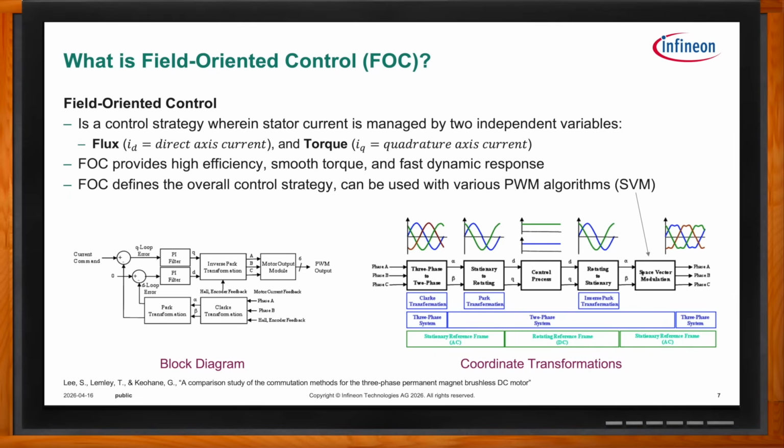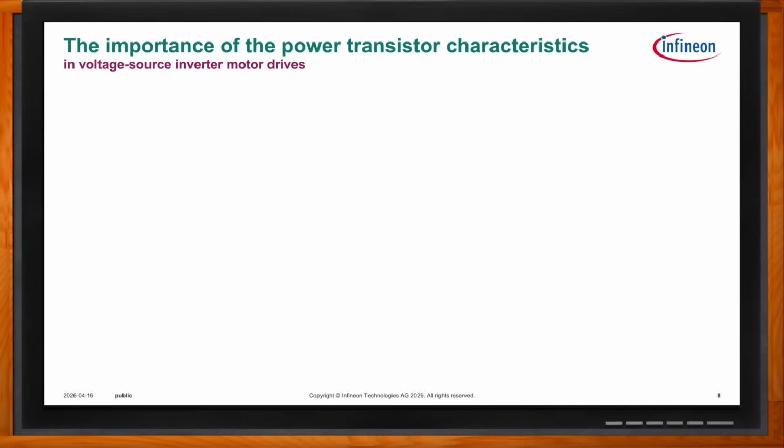So, Eric, power transistors are a very important component in these systems. Talk to me about the role they play. Yeah, so we've just seen kind of the refresher motor drive 101 here. So we looked at the machine itself, mechanically commutated, electrically commutated, the different methods we can use, and all of that. And I think it's necessary because now it'll help you understand how the inverter, the switches driving voltage and current into the motor, help with improving these characteristics we want to improve, which is power density, and size and torque ripple and all of that.